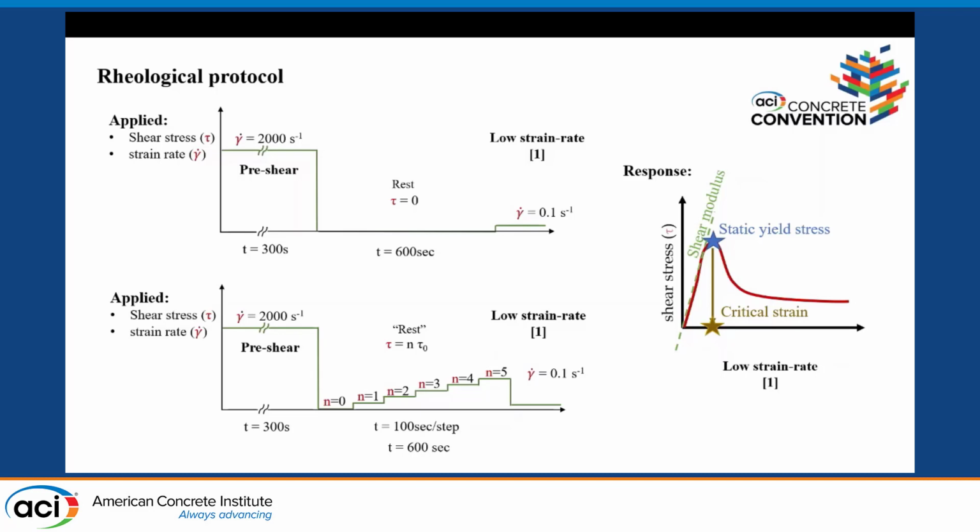In the second, I wanted to impose a stepwise function of stress at rest that is below my static yield stress. So in this step, we can assume I will have 1,000 Pascal that happens here at this time. I will try and see if I keep this below my 1,000, where would my static yield stress be? And in some cases, I was able to go even higher.